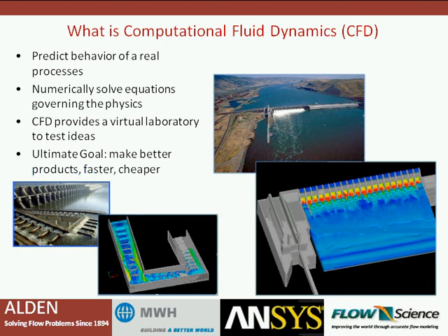And there are various means of doing this, and I'll explain how Flow3D does it as we get further into this. And then with that discretized domain, you numerically solve the equations of the governing physics. And for hydraulics, that's primarily going to be your Navier-Stokes equations and a continuity equation, and then your volume of fluid technique for free surface modeling.